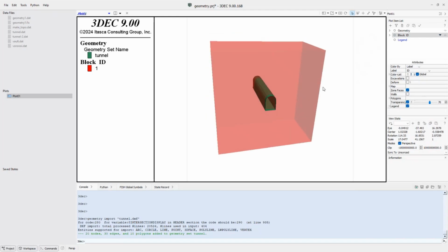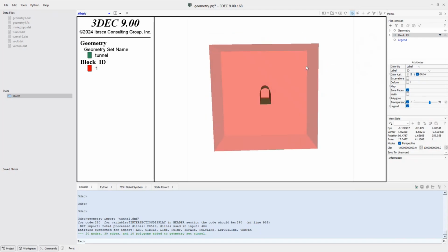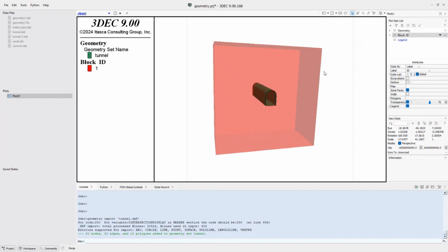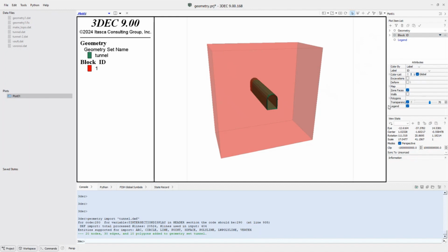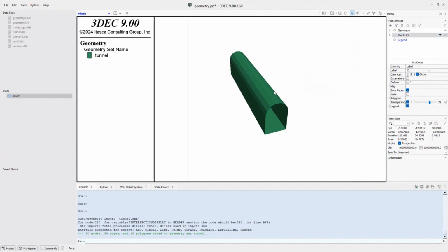Right, so this is a relatively simple case. You could actually cut this tunnel out with commands. There's a block cut tunnel command, but just to demonstrate how you can use the geometries. Note in this case that the surface isn't actually triangles. It's, in this case, four-sided faces. That's fine. It still works. So I import this geometry, and it will make a cut for every facet of this geometry. So there'll be a cut here, a cut here, a cut here. And you'll end up with a dozen or so cuts to define this tunnel.